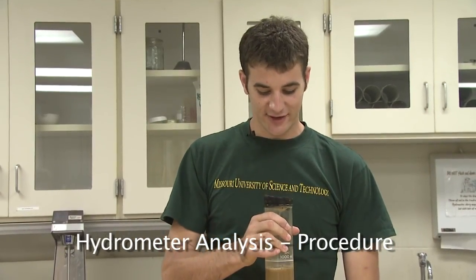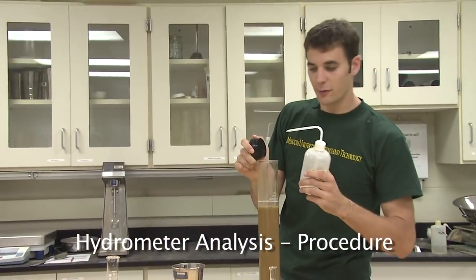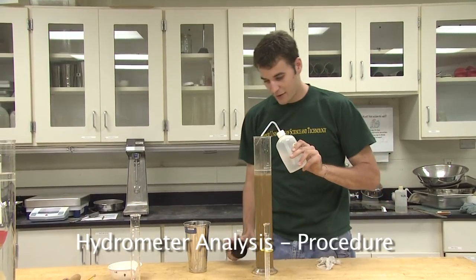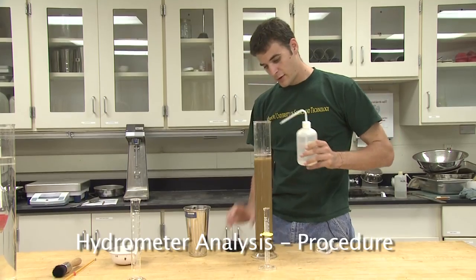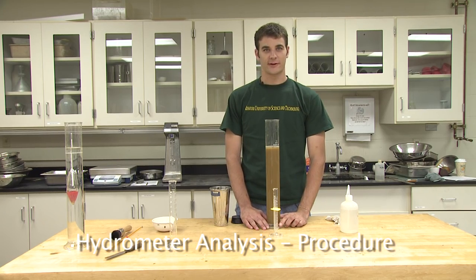After 1 minute of agitation, remove the rubber cap and use your water squirt bottle to ensure that all of the sediment is off the cap as well as off the sides of the sedimentation jar. Fill the sediment solution up till it is at the 1,000 milliliter mark. Place the sedimentation jar on a table where it will sit undisturbed for the next 24 hours.